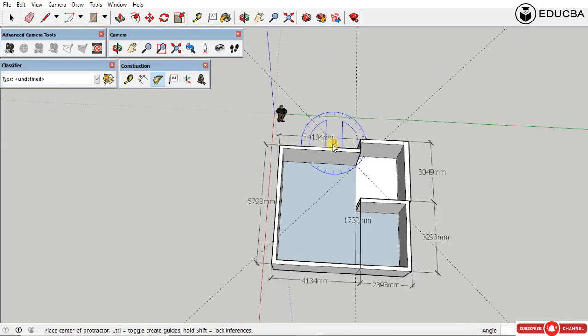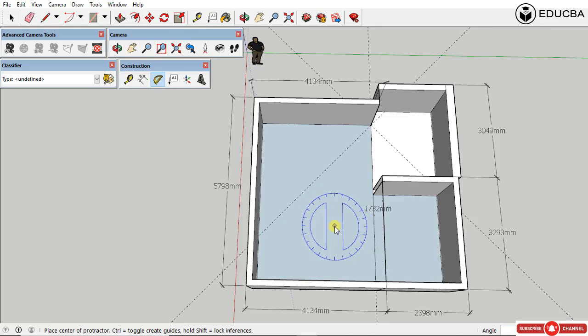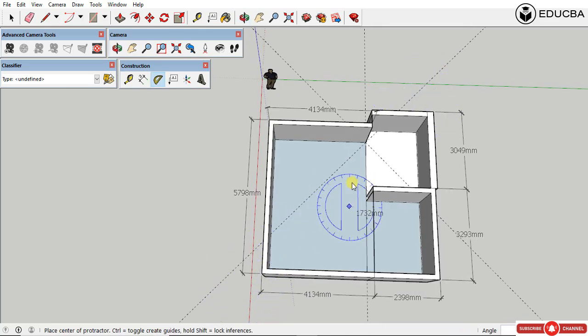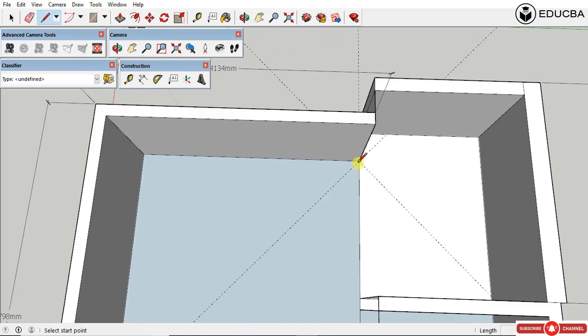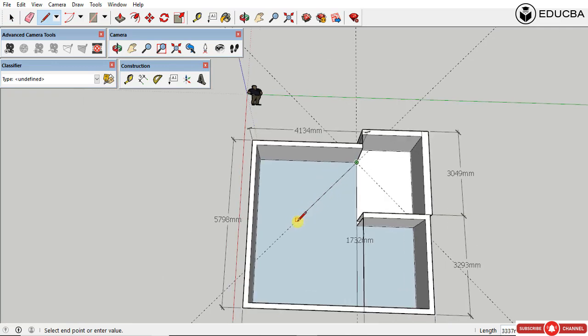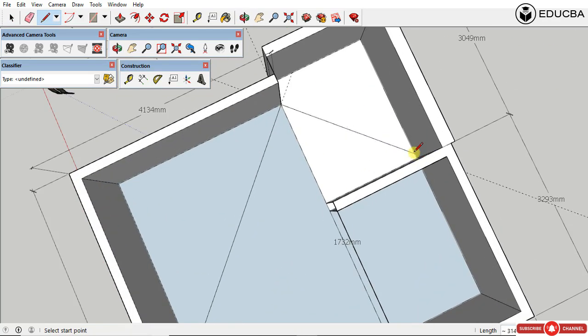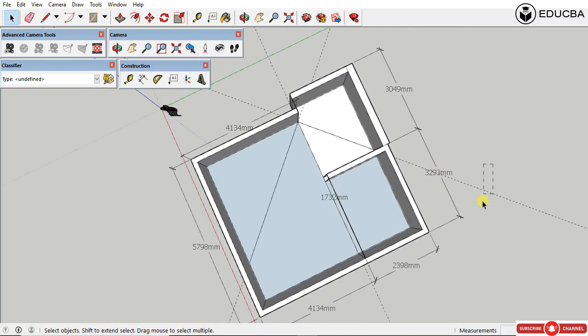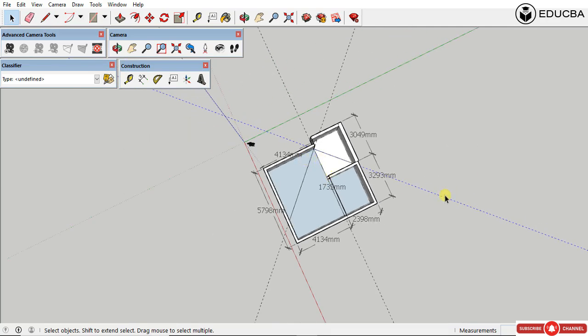Whenever you want to create an angle, these dotted lines are created as guidelines. So when you want to draw a line on this, it will follow this line. So you don't need to randomly create it. This will create a guideline for your drawings, your angular lines which you need to follow. So these act as guidelines for you to understand 45 degree. This is the line which I have to follow for 45 degree from that point. Now this can be deleted easily later.